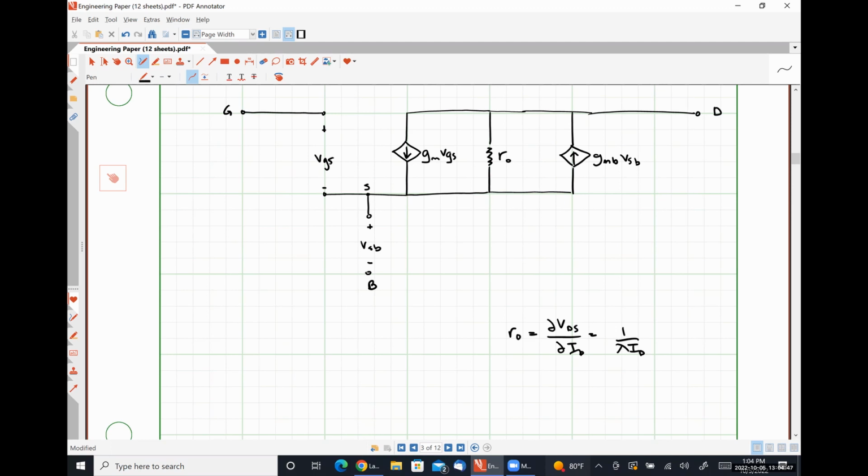And one thing that I want to point out about this particular small signal model is that we are assuming our device is operating in the midband, so that all of our internal capacitances of our device are effectively looking like open circuits, right?